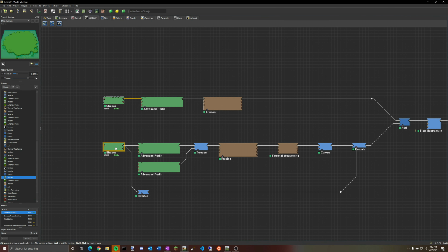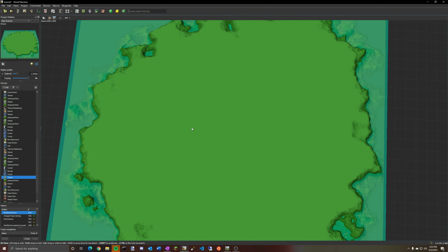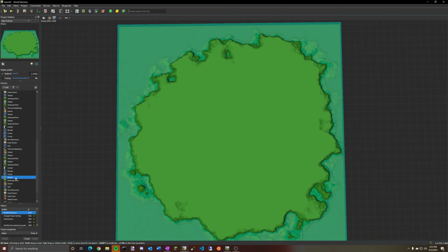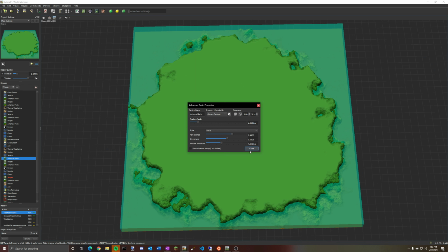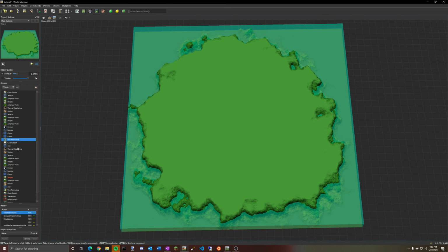So there's some final tips and tricks I'd like to go over before I do that. The first is when you're drawing these two shapes out, there's some features you can use to make it easier. So you draw this one out here, right? And then you can do something called locking the preview, and that'll make it so no matter which of these you click on, only this one will show up.